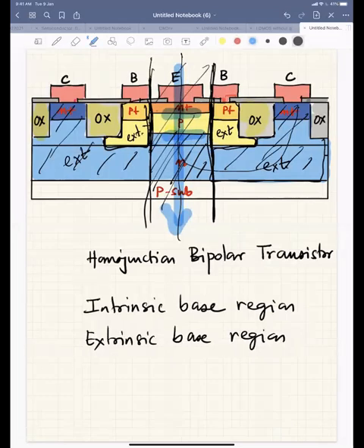But here you see these are doped. This is N plus region, this is P region, and this is N region. These are doped. This is a complicated structure to fabricate. In this cross section I have shown, you can see different color coded things, so it is not very straightforward to design. It is not very complicated, but we have several steps: implantation, oxidation, deposition, every fabrication step is used to fabricate a bipolar junction transistor, and finally it looks like this.